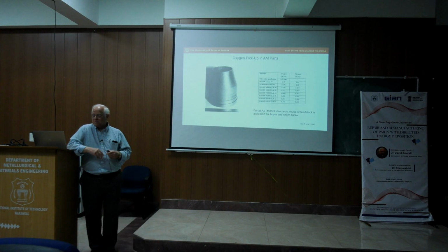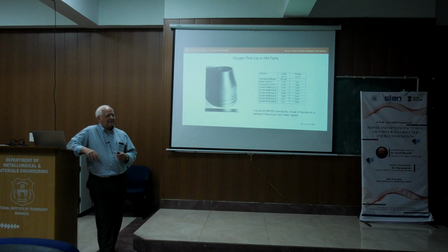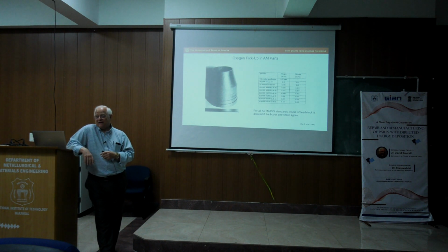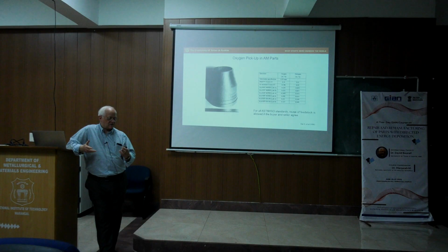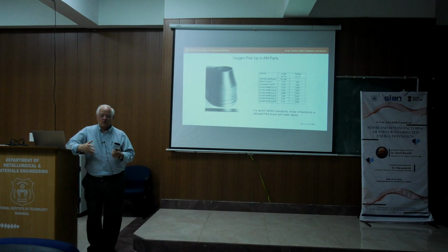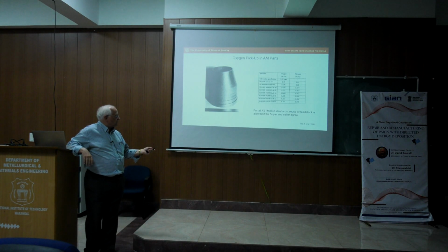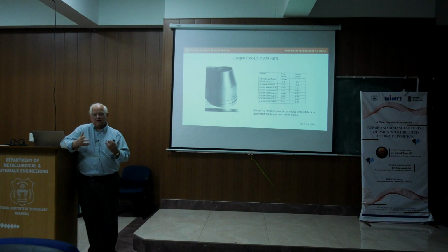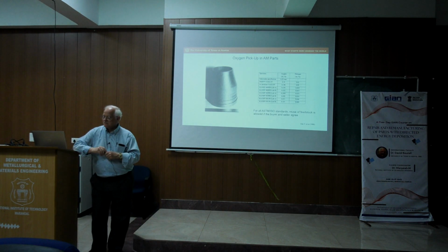We talked about some issues with satellite formation and increased porosity, some of the factors associated with reusing powder. I guess we talked about that on Monday. But the powder can be sieved, we can remove the satellites, it can be recycled. And it's okay to do that, at least according to the standards, if everybody agrees.